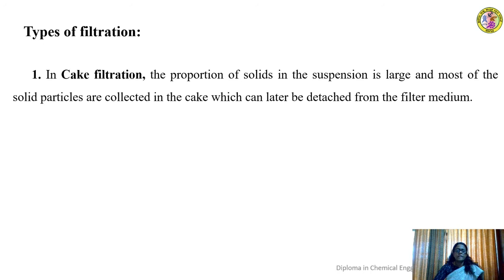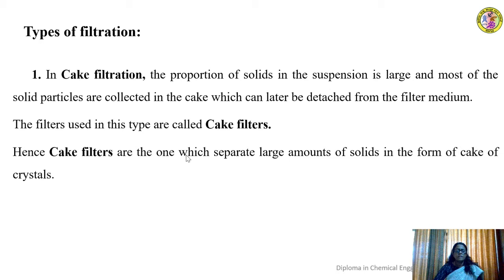When that cake gets collected up to a certain level, you need to take it out from the filter medium. Otherwise, you cannot continue the cake filtration. So the solids need to be detached from the filter medium, since the quantity of solids to be separated is large in this type of filtration. And the filters which use this kind of filtration are called cake filters.